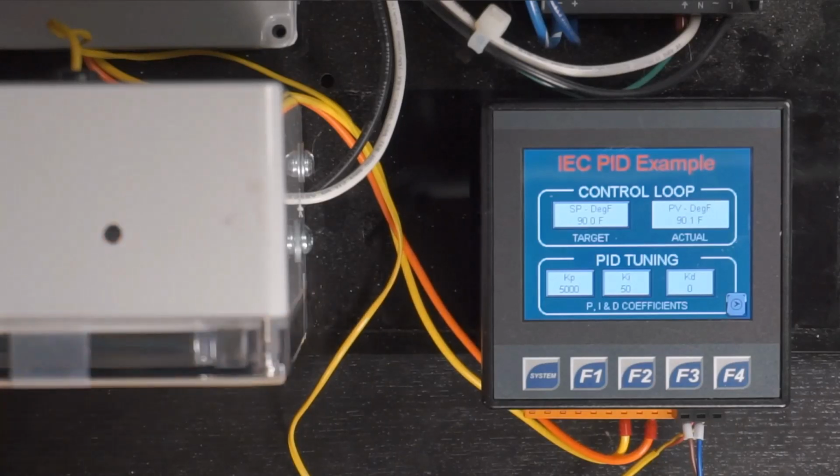Which is pretty darn good, especially since it's in degrees Fahrenheit. And then I'm showing on the screen my PID algorithm coefficients for the proportional, integral, and derivative terms, and those look awfully round. I went ahead and did an auto tune, and then I did some tweaking, and I just ended up with some fairly round numbers, and it was close enough for what I was doing. So that's where I ended up in terms of my PID tuning.